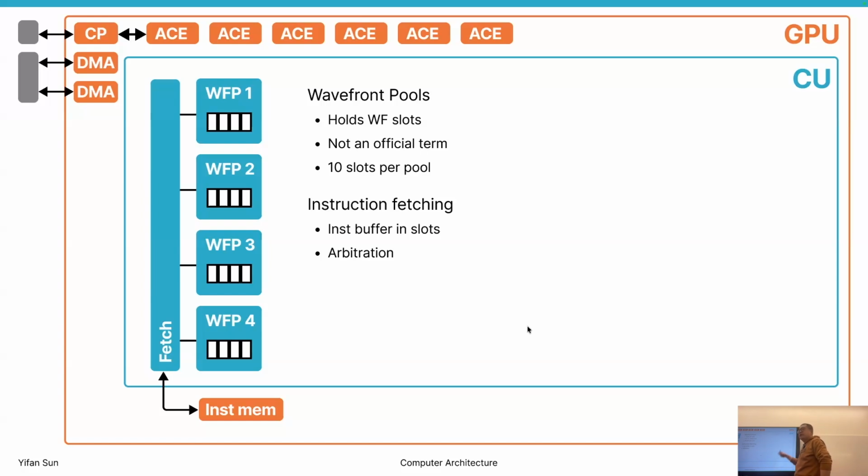the instruction pipelines. So the fetch arbiter can decide which wavefront can fetch data. There's no fixed algorithm for the fetch arbiter. There are many different ways that we can arbitrate. For example, in one way, we may want one wavefront to execute as soon as possible.